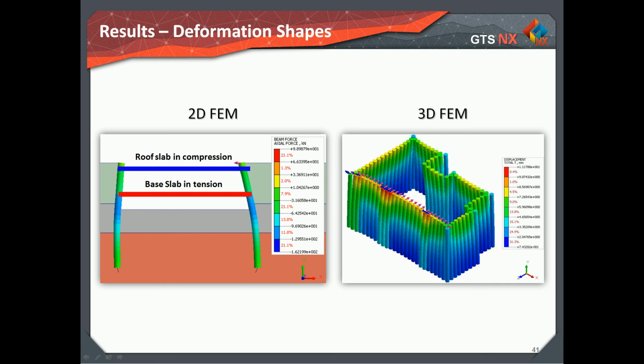This situation is due to the deformation shape of the walls and slabs as one structure when subject to line and moment loads at the piles, resulting in an asymmetric profile. Limit equilibrium model assumes a symmetrical behavior and ignores the 2D geometry of the structure along with the associated load path.